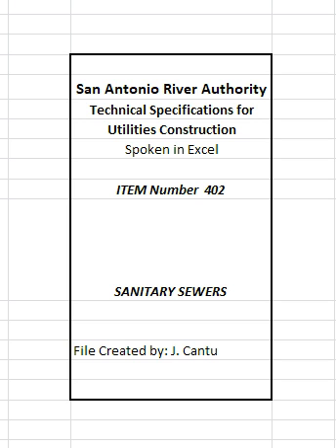Pipe wall thickness and outside diameter shall be tested and shall meet the requirements established in the respective ASTM standards as measured in accordance with Section 6 and Section 8, respectively, of method ASTM D2122. Pipe wall thickness and outside diameter for AWWA C905 pipe shall be tested and shall meet the requirements established by the AWWA C905 standard. Other pipe approved for use with a different pipe material, different diameter specification, or different allowable percent deflection shall have a mandrel configured accordingly.